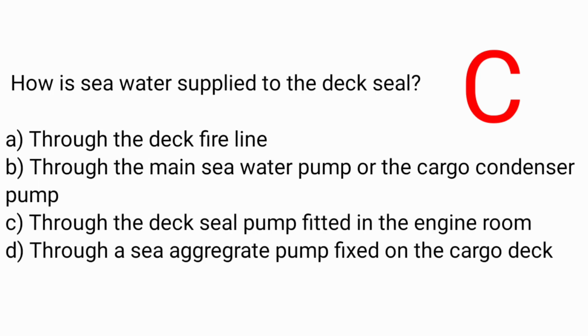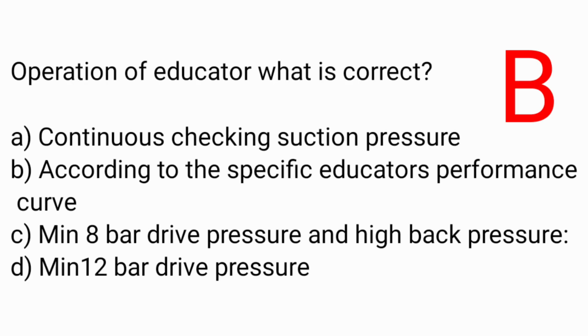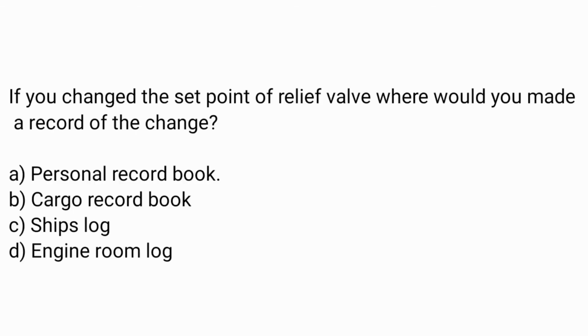How is seawater supplied to the deck seal? Answer C, through the deck seal pump fitted in the engine room. Operation of eductor, what is correct? Answer B, according to the specific eductor's performance curve. If you change the set point of a relief valve, where would you make a record of the change? Answer D, engine room log.